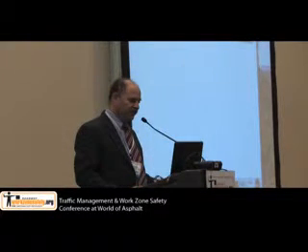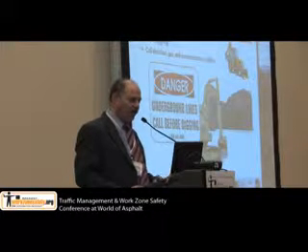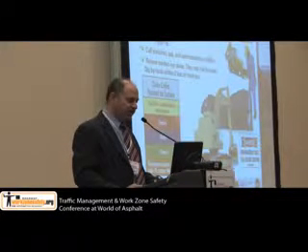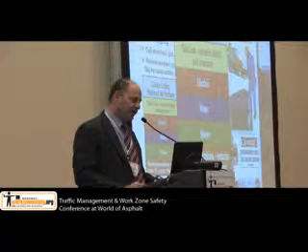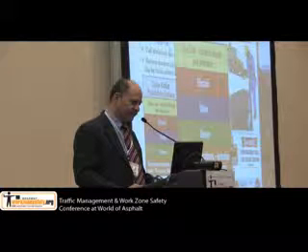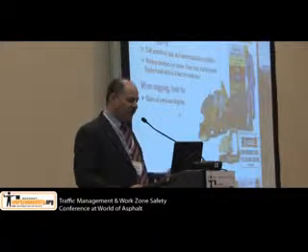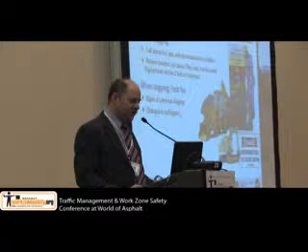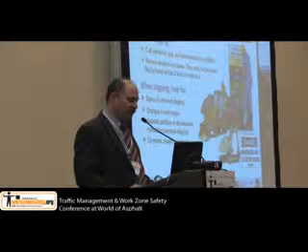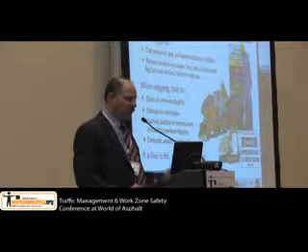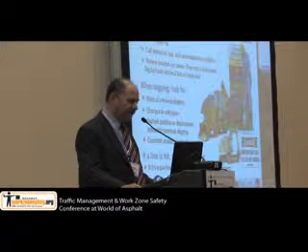Okay, and around buried utilities, before you're digging, again, call the utility company. These are the standardized codes for coloring where lines are buried. What to look for: if you see signs of previous digging or changes in soil types, asphalt patches, depressions, concrete, plastic, or gravel, it indicates there might be a line there. And if you do hit a line, you should report it immediately to the fire department.